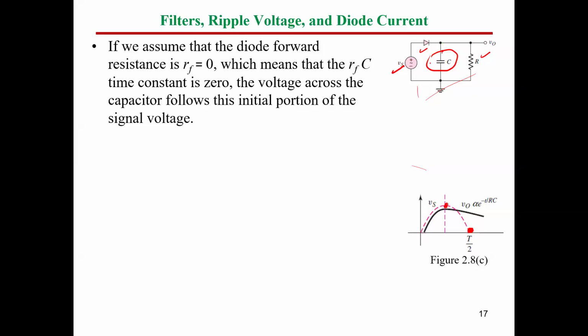So when the volt at the anode side is greater than the volt at the cathode side, which is theoretically equal to 0 in the beginning, this means in the positive half cycle, once the volt at the anode side is greater than the turn on volt, let's say 0.7 for instance, this diode will be turned on.